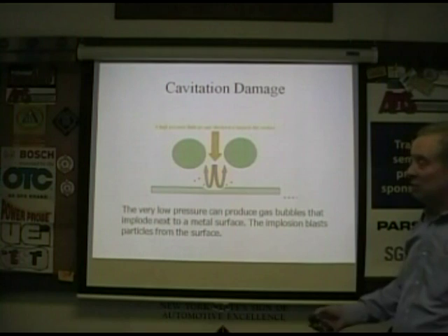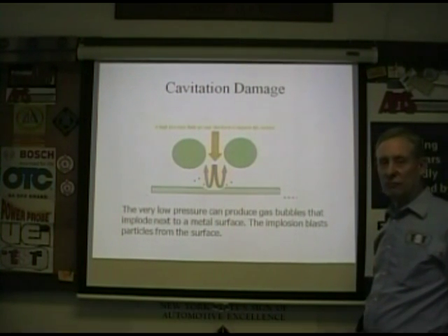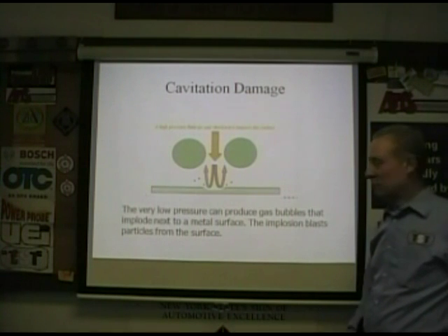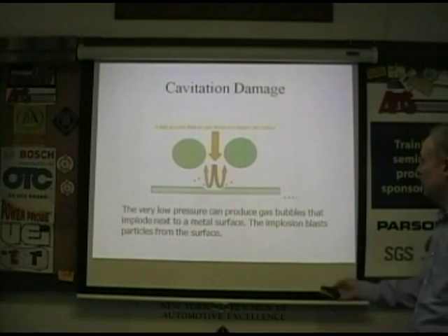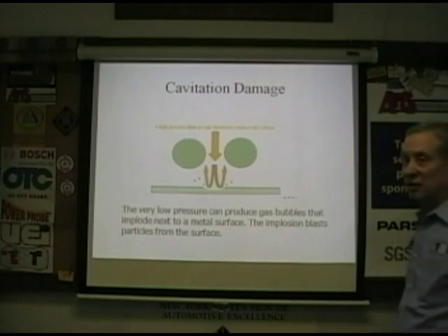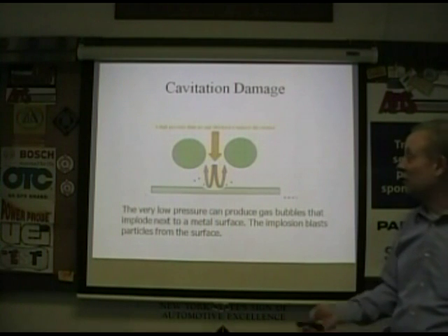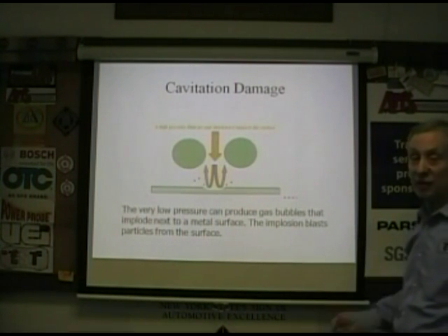Look for collapsed hoses, which sometimes will tell you you have a bad cap. That is one of the things that is good to take a peek at. This is the phenomenon I was talking about. The air bubbles are exploding. It sounds crazy, but it's been proven to be extremely dangerous to materials. In fact, they use it in manufacturing to cut materials.